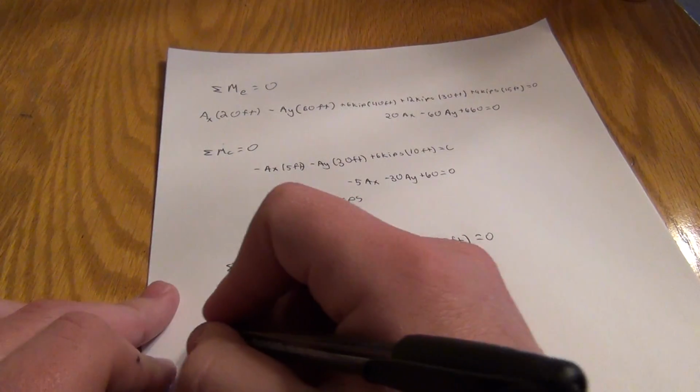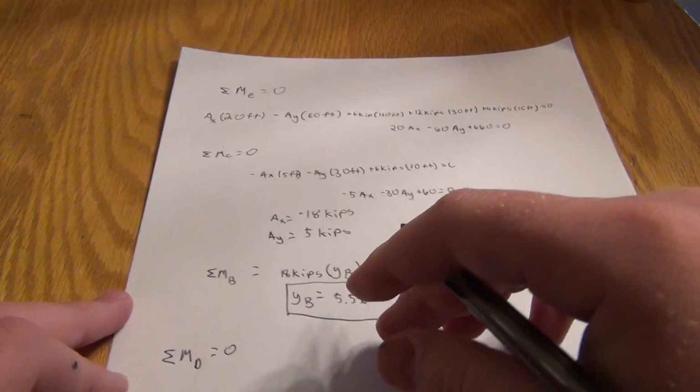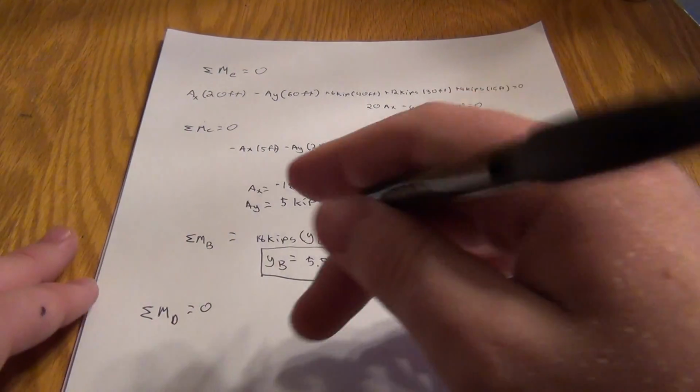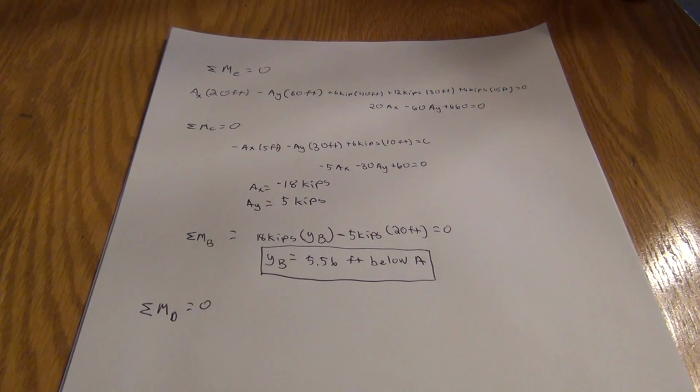So, moment around D is going to equal 0. Okay, that's just basic equilibrium. So, first component in our equation, let's look at it. Moment around D. So we have 18 kips, a distance, elevation YD. So that is our AX component, and then since AX is a horizontal, our vertical distance from the component AX to D is the height YD. That is what we're solving for.